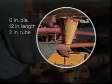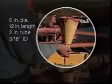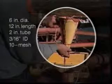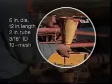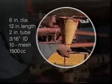The funnel viscosity of the mud is measured using a Marsh funnel and graduated cup. This apparent viscosity measurement is used to indicate relative changes in mud viscosity. The funnel is 6 inches in diameter at the top, 12 inches long, and tapered to a tube 2 inches long with an internal diameter of 3/16 inches. A 10-mesh screen is fitted across 1/2 of the funnel top to filter out foreign matter. The capacity of the funnel is 1,500 cubic centimeters.